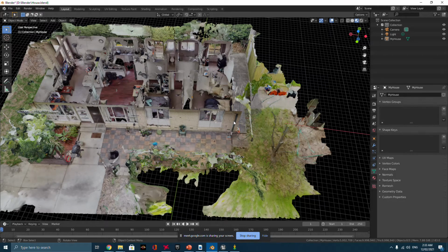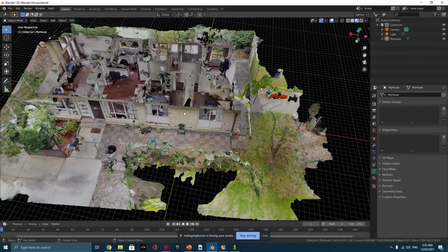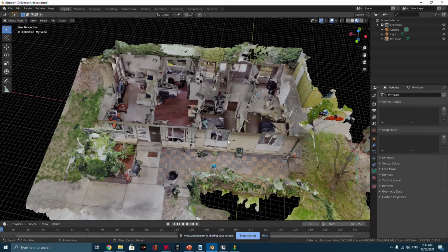So then you can align them on either the point cloud or on the camera position. If there's a camera position that is shared by both chunks, because you actually put the photos into that chunk, you can align them on the camera positions. I had tried that before, and it worked. So you mean to say the reference point should be in all pictures, to join by edge match? Yeah, you can try and join them, but it's not always successful. It just really depends. In this occasion, it was, but if you weren't able to, you would have to maybe do them in separate chunks.